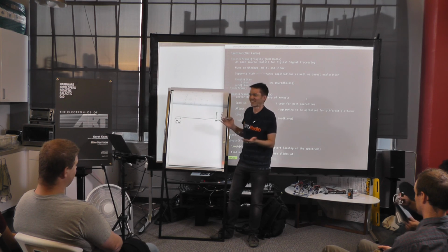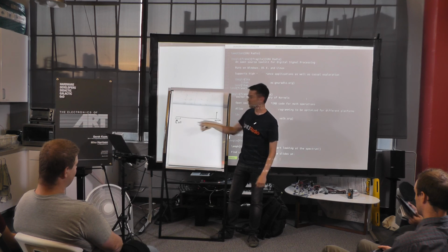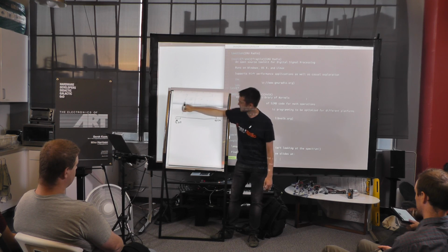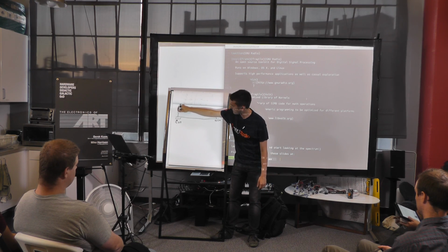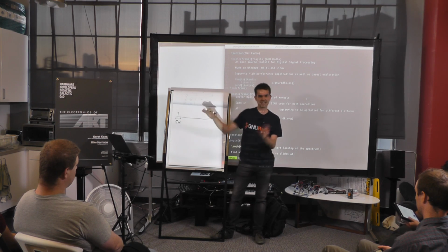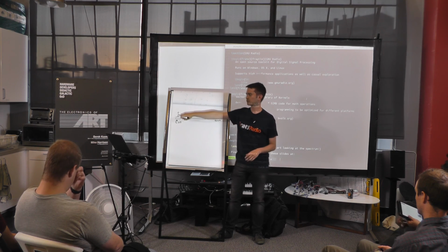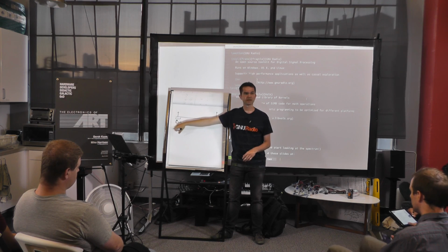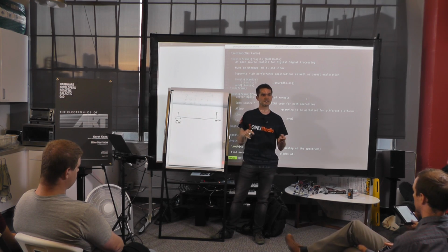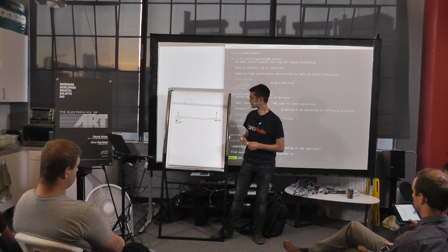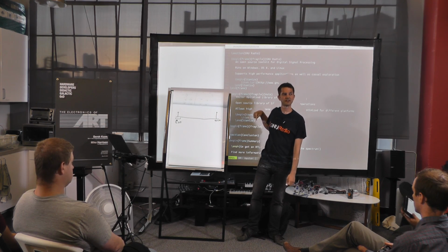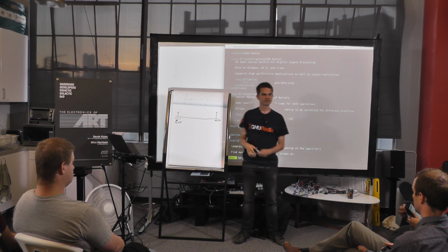Hey, I've got a minute here. If you tune that oscillator to be 98.0, it'll take this signal and it'll produce a copy of it at half the amplitude and some loss and other things right down at your frequency, right down in your baseband. So that's again your baseband here. And so that's what we were seeing happening. And then entertainingly, you would end up with another copy of it up at almost 200 megahertz, 199 and change.